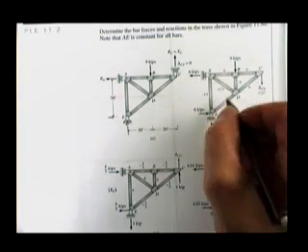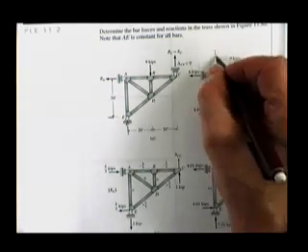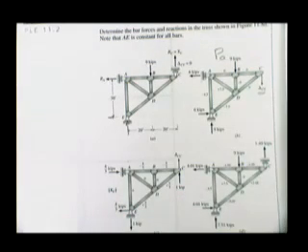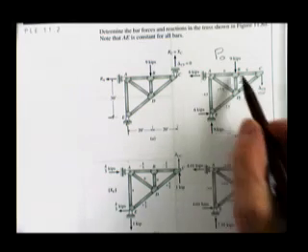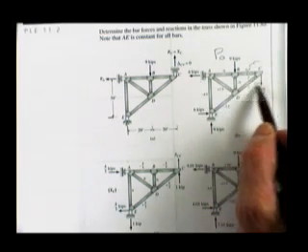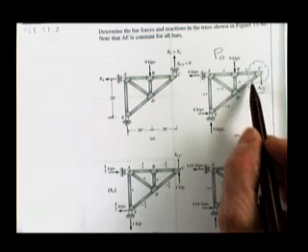So you have an M0 diagram. Probably call it a P0 diagram. It's a diagram of all the forces inside of the structure due to the real loads applied to the released structure, and you find all the forces inside of those members. Method of joints will tell you the force in member BC and DC. He has listed 0 and 0.